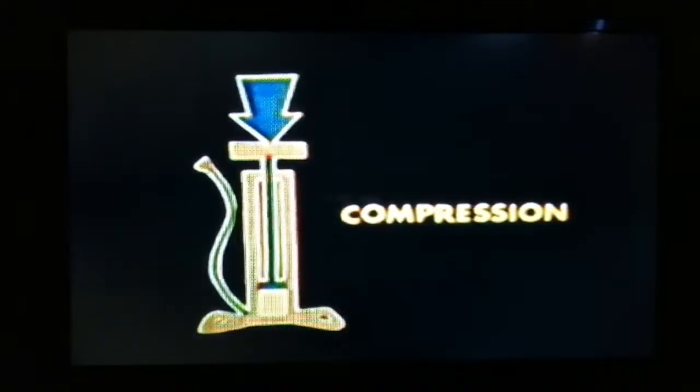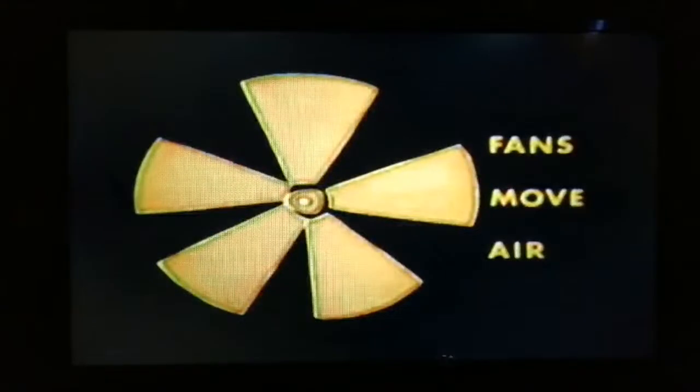This is called compression. In the broadest sense, air compressors include all devices used for raising the pressure of air. Seldom spoken of as compressors are fans and rotary blowers. They are used mainly for moving air rather than compressing it. In some applications, air may be compressed to several thousand psi. The working pressures used in power plants usually average 100 to 115 pounds per square inch gauge.